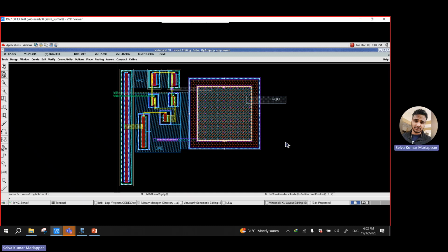Okay, so in a more advanced level, like the pin sites, for this PDK we are using text layers to place the labels. But for TSMC and GlobalFoundries, everything is going to be different. For TSMC, we normally use the pin layers, metal 1 pin, metal 2 pin, to put the labels. So it depends on the different PDKs. That is why whenever you get your PDK, the first thing you do is study the PDK, study the documents, study the components. That's the first thing you do before you design your schematic.